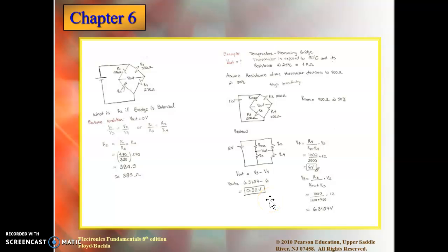volts. So the voltage is very small, but because we are in a balanced state here, we are able to pick that out, and then we can have lookup tables that say, okay, when we are reading this voltage, that voltage is mapped into this temperature. So that's how actual thermostats work in your house. It's not like they actually measure the temperature. They are associating that voltage reading to a temperature so that you can see a number that makes sense on your digital screen at home. So that's how it works.